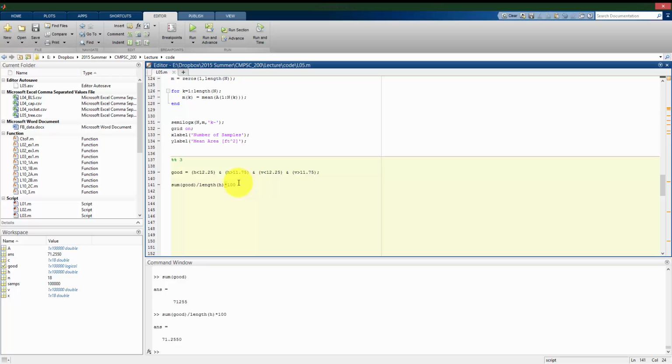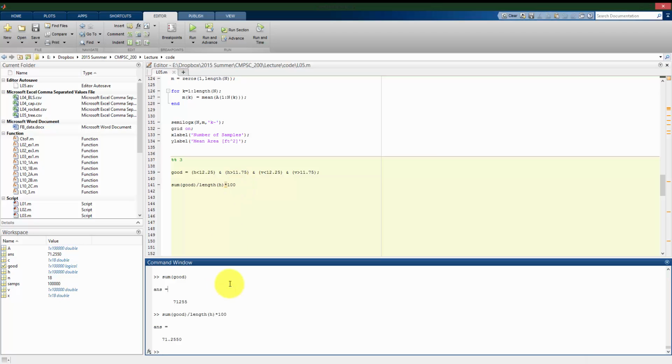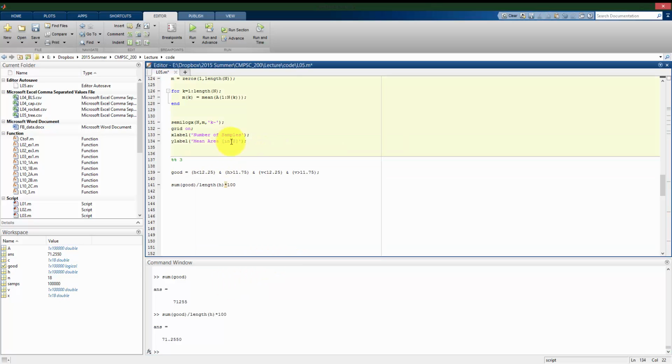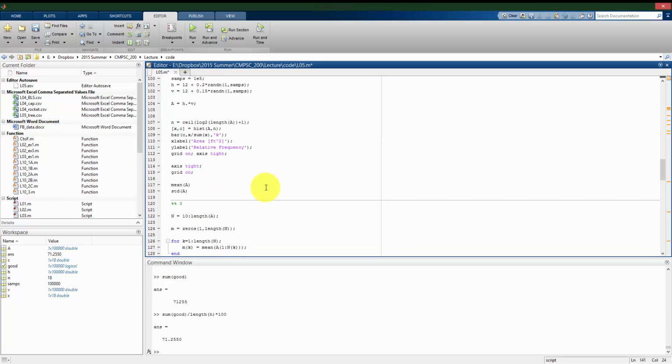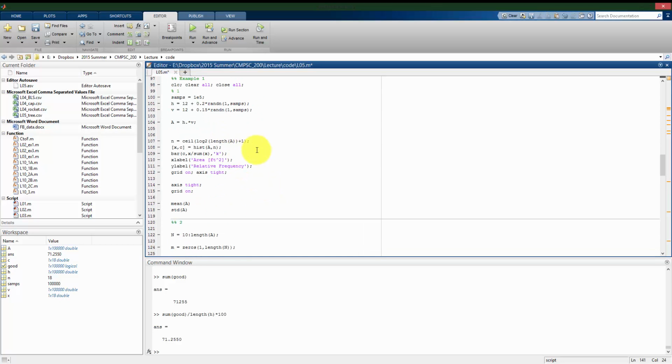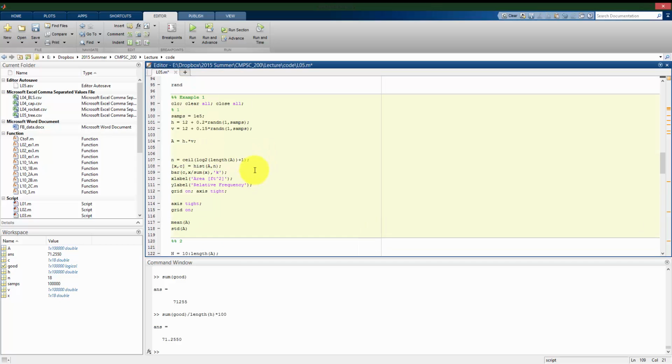Now, where is this useful? Well, if I know that this is what my buyers want, within plus or minus 0.25 of 12 inches, and this is my manufacturing process, and I'm seeing I have to throw away 30% of the tiles, this would tell me as the manufacturer that I would want to look at my manufacturing process and tighten up those tolerances. So let's go a little bit further than what the question asks.